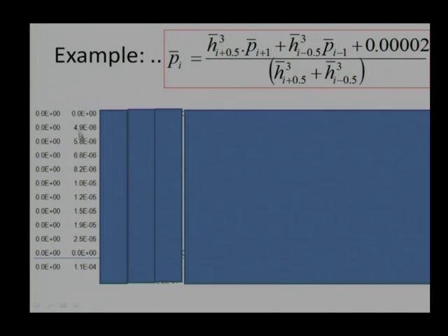So, sequentially we go ahead and get the values, and we are able to see the pressure value is continuously increasing. There is already one source term plus an increase in the pressure term, so compared to 0 it will be a higher value. That is why the pressure value is increasing to a maximum up to node number 10. Of course, node number 11 is a boundary value, and we have already specified that the pressure value will be 0 there, that will not change with any iteration, it will remain the same.